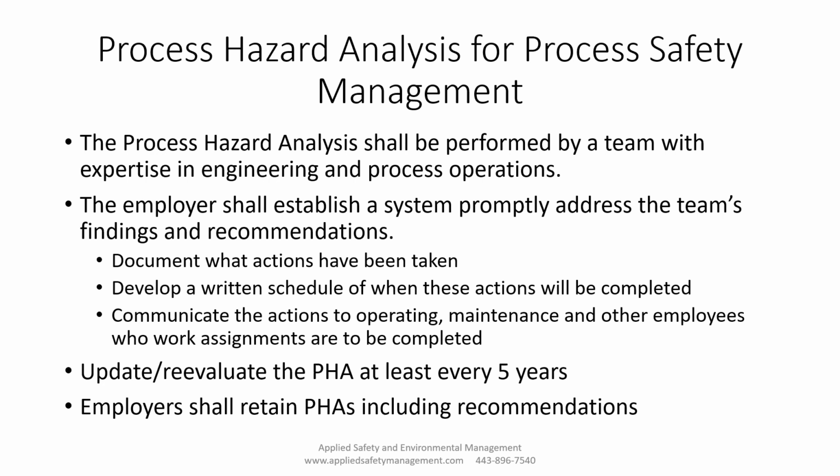So the process hazard analysis shall be performed by a team with expertise in engineering and process. The best thing that I found is that you find the operators and the maintenance people. They really know what's going on. They can tell you everything about the process and hazards that maybe you didn't really think was a hazard or a big deal, but they can really point out these things.